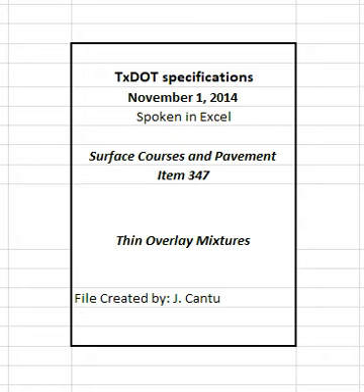4.9.2.4.4 Hamburg wheel and overlay test. The engineer may perform a Hamburg wheel or overlay test at any time during production, including when the boil test indicates a change in quality from the material submitted for JMF1. The engineer may obtain cores and perform the Hamburg wheel test on any area of the roadway where rutting is observed in addition to testing production samples.